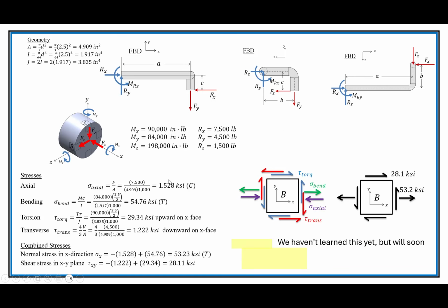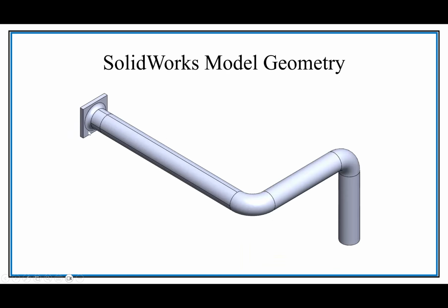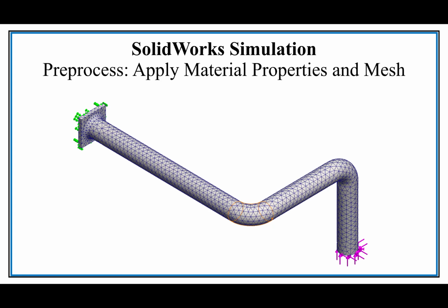I have cut this thing up with these split lines. I've also moved it away from the wall. You can see there's a fillet at the wall, but I have made it so that this exact point right there should match up with what the problem is. I want to make an apples to apples comparison.